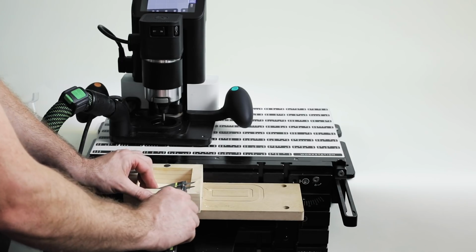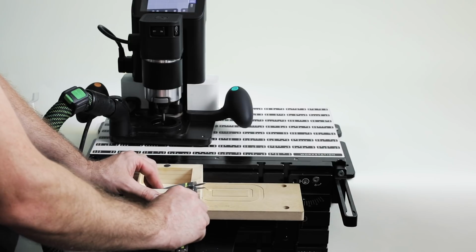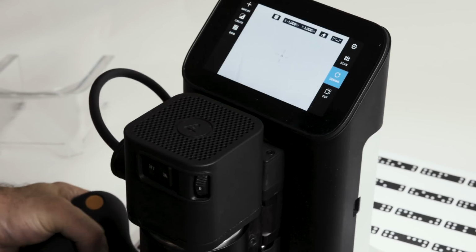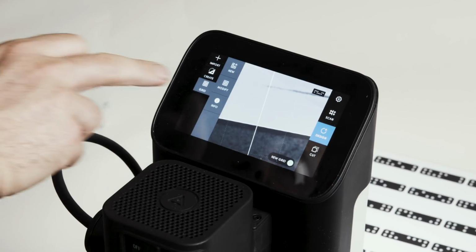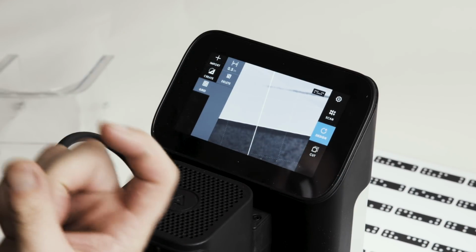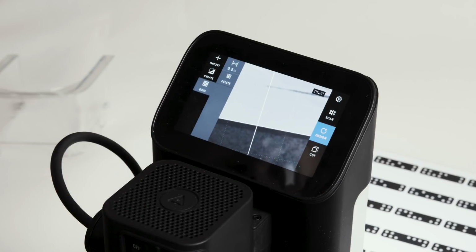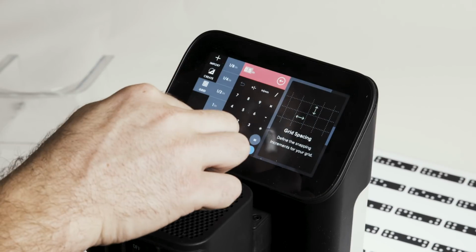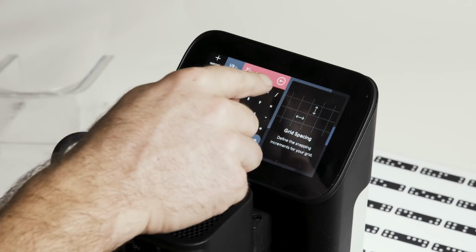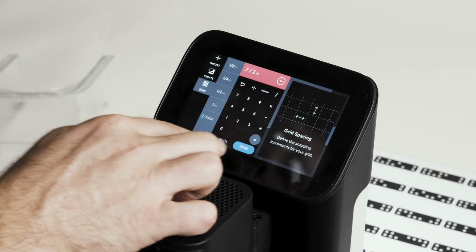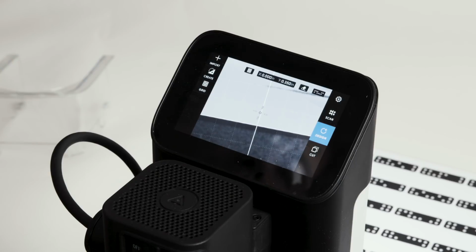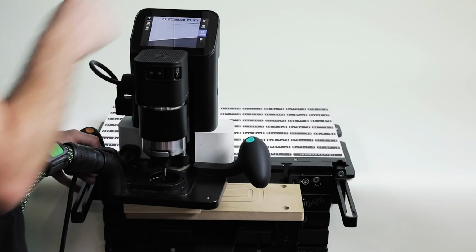Next step is we'll measure this to 0.7. So I'm going to center it in this stock. To identify the center point of this stock, we're just going to let Origin help us out here. With Grid Modify, I can create an increment that is half that dimension. In this case, it's 0.7, so it's easy math, divided by 2. We could just enter it, but if it was some pretty complicated decimal, it's nice to be able to do this. So I just divided that by 2, which means the center point here is exactly centered in my stock.